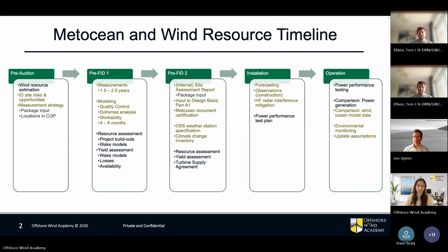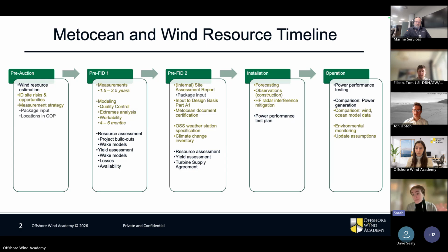special attention. You can say that an offshore oil rig has a lot of subsea components, but you only go up maybe 100 meters into the air, whereas for offshore wind, you're talking about 30, 50, 100, very flexible 150-meter towers that are all spatially located maybe across a much larger area. And so the accessibility needs for boats, the orientation of your boat platforms, they're all things that have to be considered based on the correct assessment of not only the weather, but also the climate.